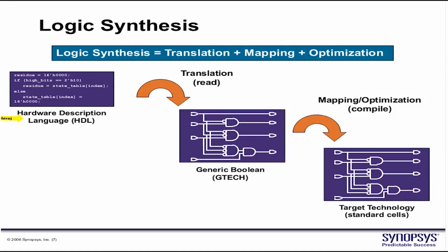So now the hardware description language, the Verilog code on the left hand side, would consist of higher level language constructs: if else, case statements, always blocks, and so on. This HDL here, the RTL here, is actually technology independent. That means it does not matter what technology node we are targeting. The RTL does not need to represent that. When I talk about technology node, I mean, let's say we are targeting either 90 nanometer or 65 nanometer, where the nanometer length is the transistor channel length.